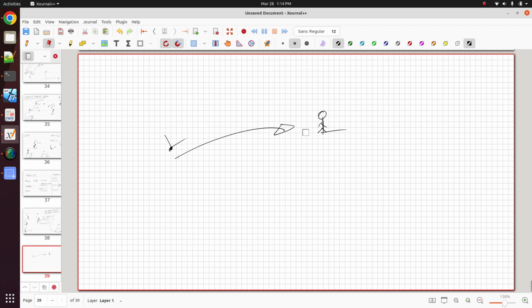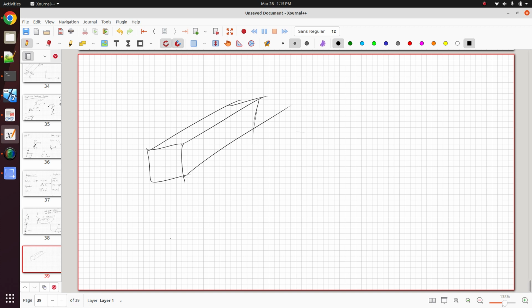And the same is true for a beam element. So when you have a beam element, it's the same thing. X would be in this direction, X element. Maybe your Y is like this, and then your Z element looks something like this. So here, again, there would be an observer. And when you look at your shear forces or your moments, you're observing these beam results from this observer.